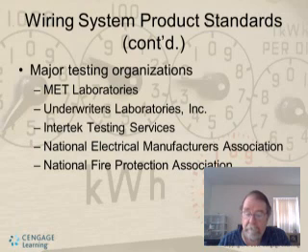And again, we talked about luminaire. It's an international term for lighting fixture. It's defined in Article 100. A luminaire is a complete lighting unit consisting of a light source such as a lamp or lamps, together with the parts designed to position the light source and to connect it to the power supply. Okay, so it's a full package. All you have to do is provide power and it should come on. It can be as simple as a light socket, or it could be something as complicated as a fluorescent light fixture with ballast, transformer, items like that.